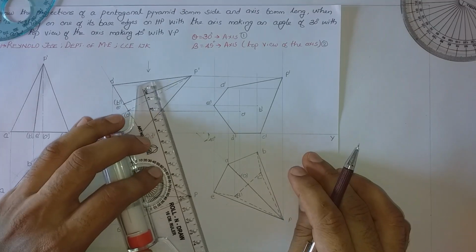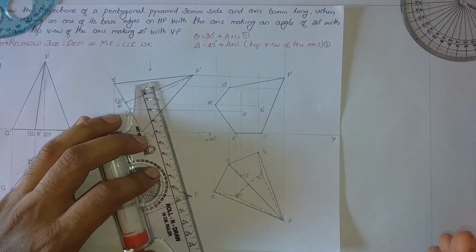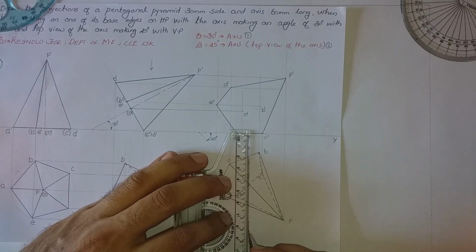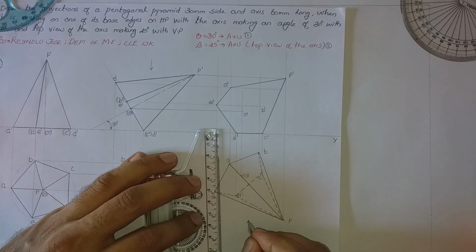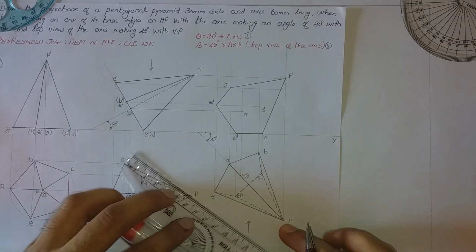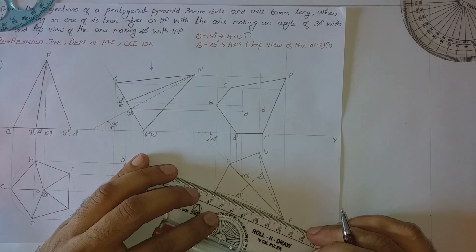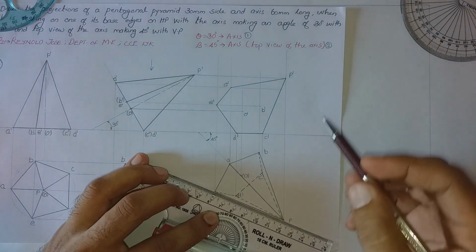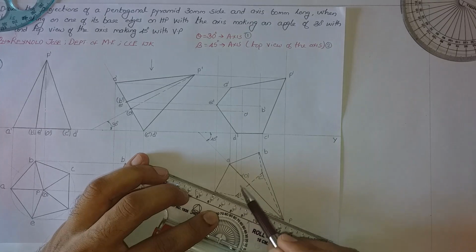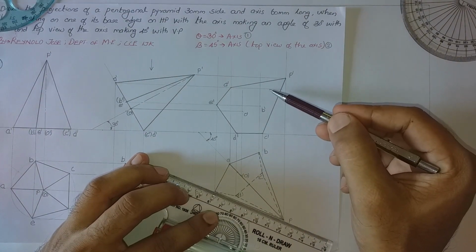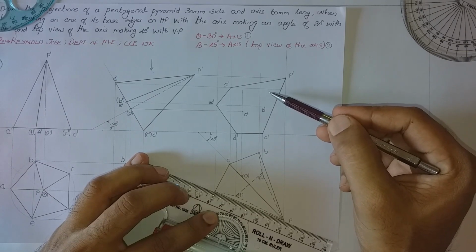Now next step is drawing in. We have to find out invisible corners. So we shall observe this top view. On the extreme left it is E and on the extreme right it is P. So connecting these 2 points, already we are having a straight line here. So between this straight line and the XY line we are having points A, B, C, D and O. These points may be invisible in the front view if they are not a part of the outline. So we shall check it one by one.